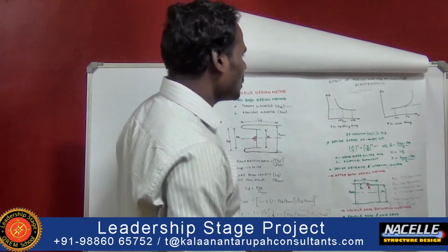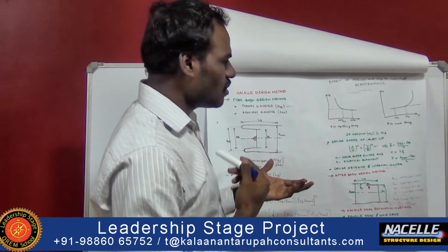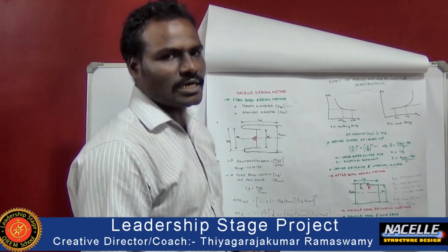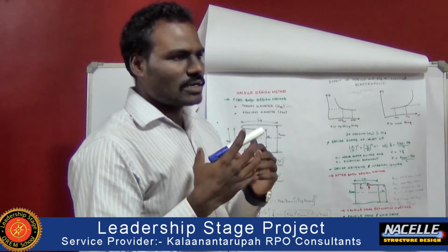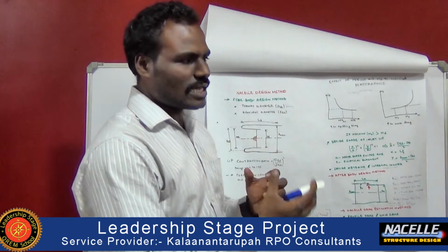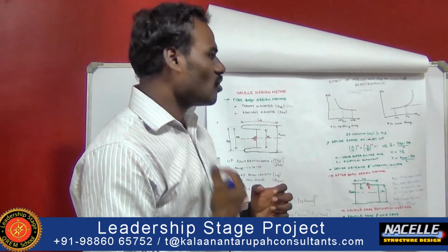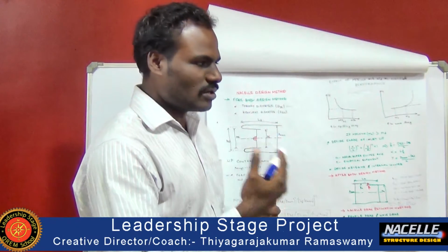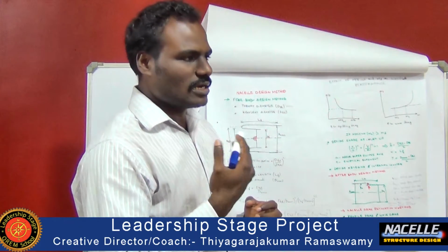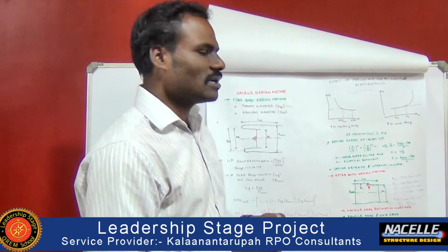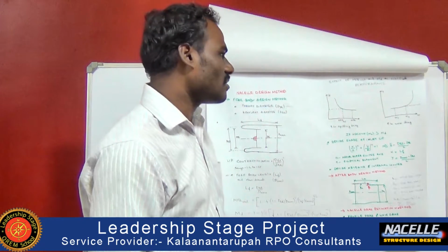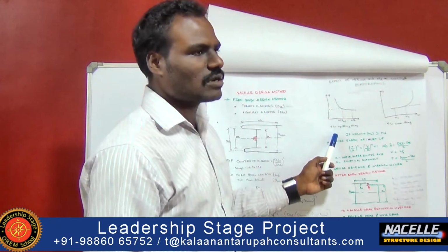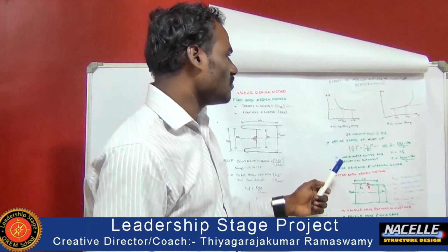Here, with respect to the increase in the mass flow, if the mass flow rate is lesser than the critical mass flow rate, then it helps us in reducing the spillage drag, in the sense when the gases extracted by the engine are more, it results in separation of the flow of the gas, which results in reverse thrust, which spoils the efficiency or the performance of the aircraft. So we have to design on the basis which will give a better performance of the engine.